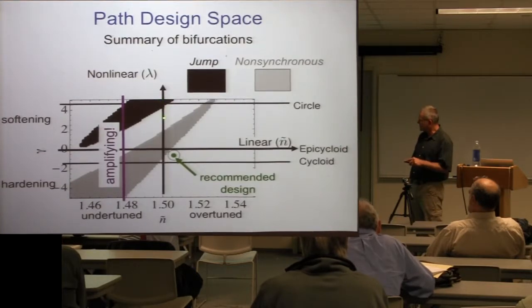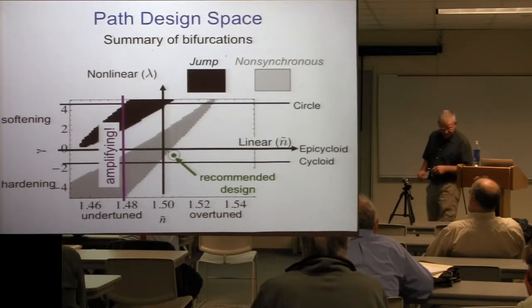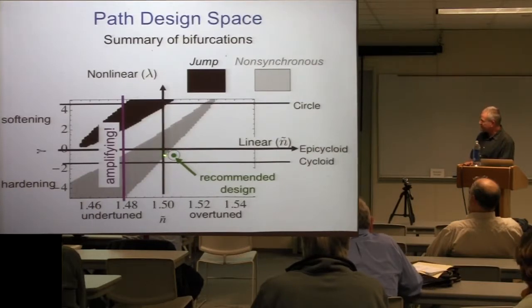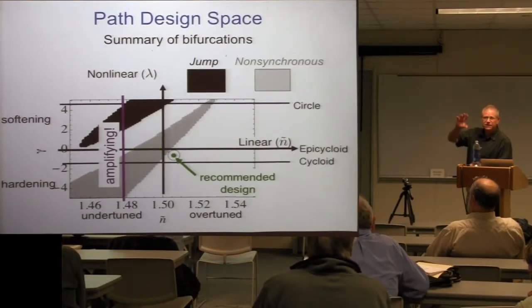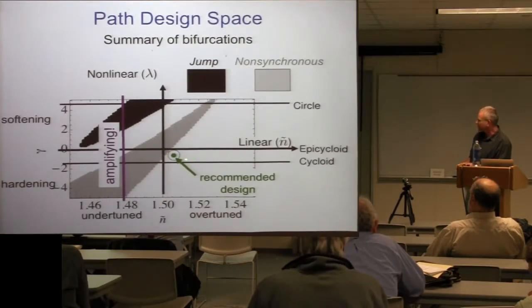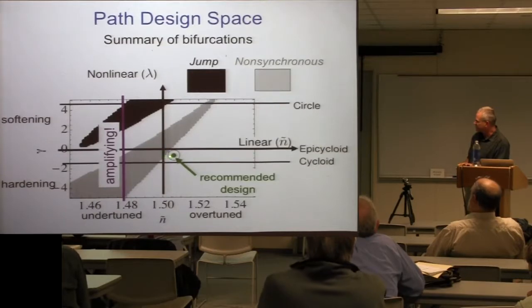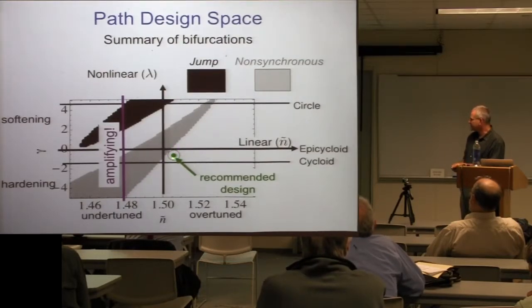But if you start to detune negative, here's the thing, that if you make a perfectly tuned epicycloid, you still have this instability. So the way they think about these designs is that they actually off-tune in this direction. And one reason is that when you go in this direction, you actually increase the torsional vibration level. I should show contours on here. Torsional vibration. Basically going this way, going nearer the center, you decrease. Going this way, you increase, and going this way up to a point, you decrease. But the point is you get as close to this instability as you can, but you off-tune a little bit linearly. And I must admit that generally, I'm not giving away big secrets here, but Ford is essentially doing here and Chrysler is doing up here.